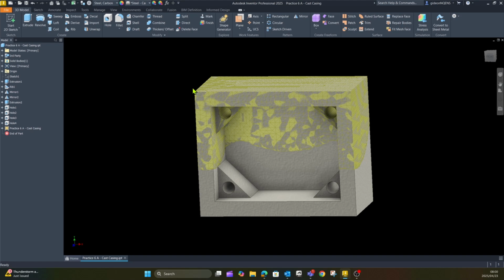Now obviously when it comes to this type of study, it's very important to keep in mind that you'll still need to just do actual FEA analysis just to confirm the results and that everything is working, and when you make your modifications to the model, that it is actual practical modifications that you are making to the model.